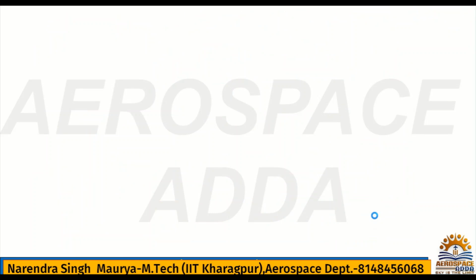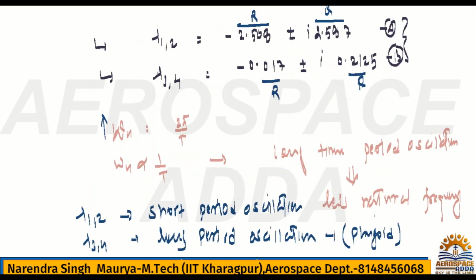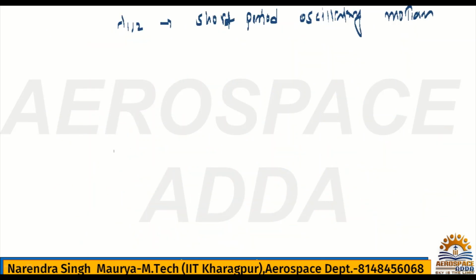Okay, so let us see. First we are going to take short period oscillation, lambda 1,2. If you check here, lambda 1,2 is nothing but minus 2.508 plus minus imaginary value 2.587.